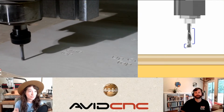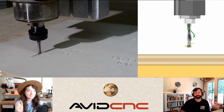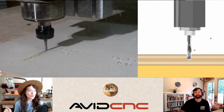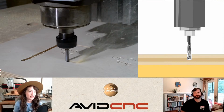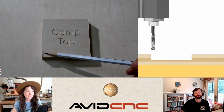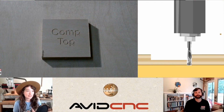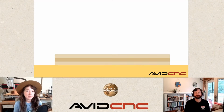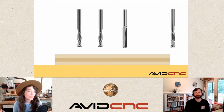With a compression bit, you have the geometry of the down spiral and the up spiral on the tip to consider. So you want to make sure to plunge your compression bit below the surface of the veneer so the upcut portion does not make contact with the top surface of the veneer. And when we go into our tool paths later, we'll demonstrate how to change the path steps here. And then you want to consider the shank type, and is it a tapered bit? Are we doing a ball nose bit for finishing? And what results is that going to give us depending on other variables we might consider.